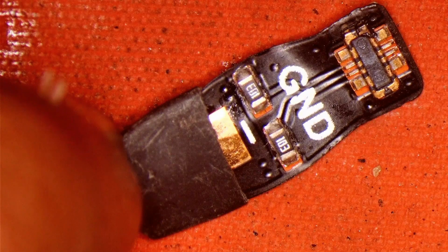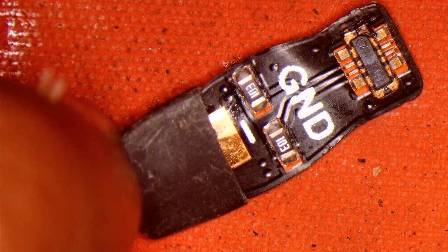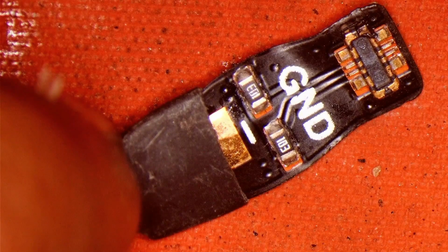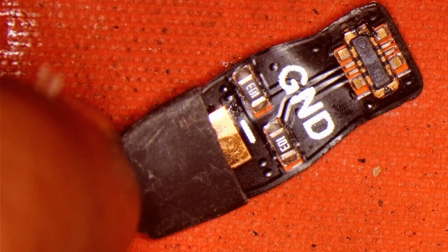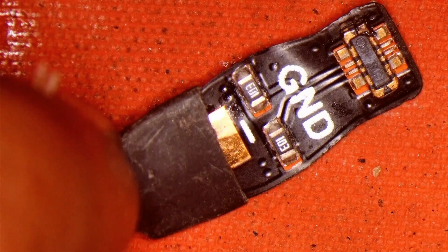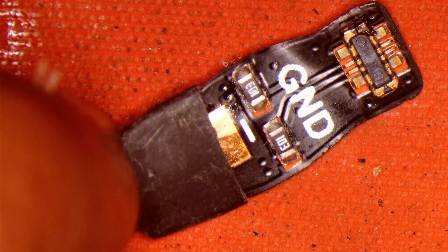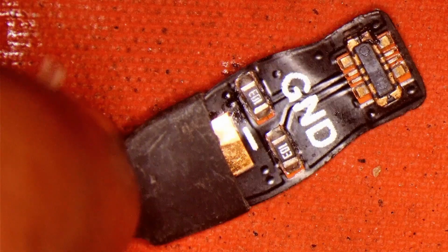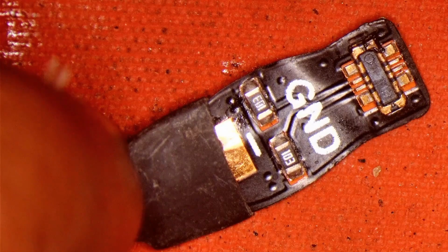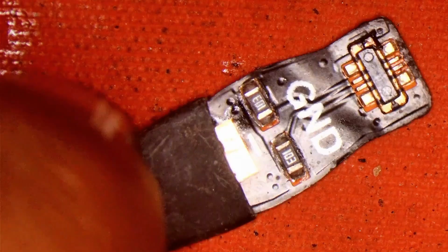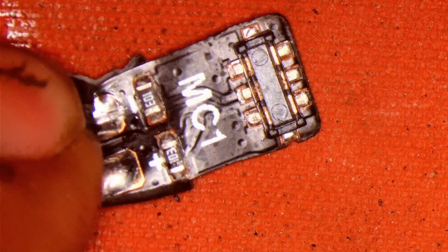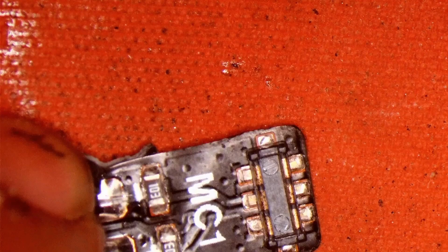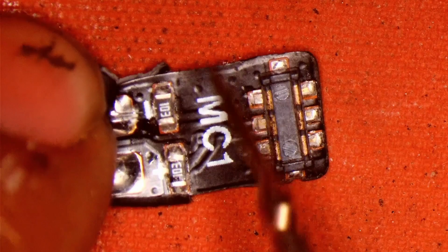Those people who know the divider circuits, in my previous videos I discussed the divider circuit. I already made a special video on the divider circuit where I taught you how it works. So R2 on a battery, on most phones, is connected to the ground. So these two resistors are connected to the battery ground. I will show you. My multimeter is on beep mode. Now look at this strip. There are two similar resistances, one for the bat ID, one for the bat thermal. Now these two resistors are connected with the ground.